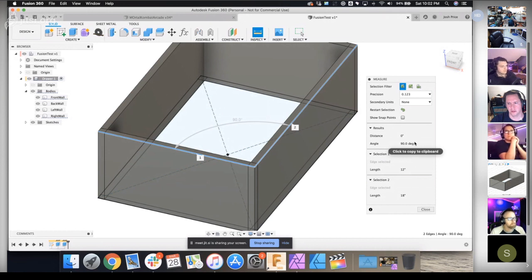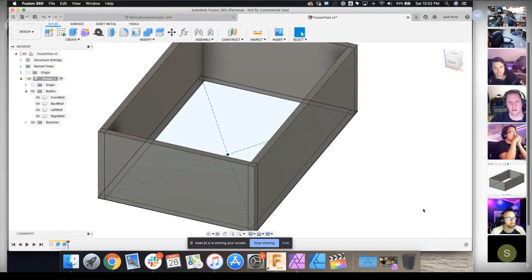So you can write this down on a piece of paper. You go, I need to go to the miter saw, and I need to cut 2 pieces that are 12 inches long, 2 pieces that are 18 inches long, and then cut a whole bunch of finger joints, and I will have this created out of 1/2-inch plywood. Hooray. Yay. But let's make this mimic real life, and this is a drawer, so let's use box joints.